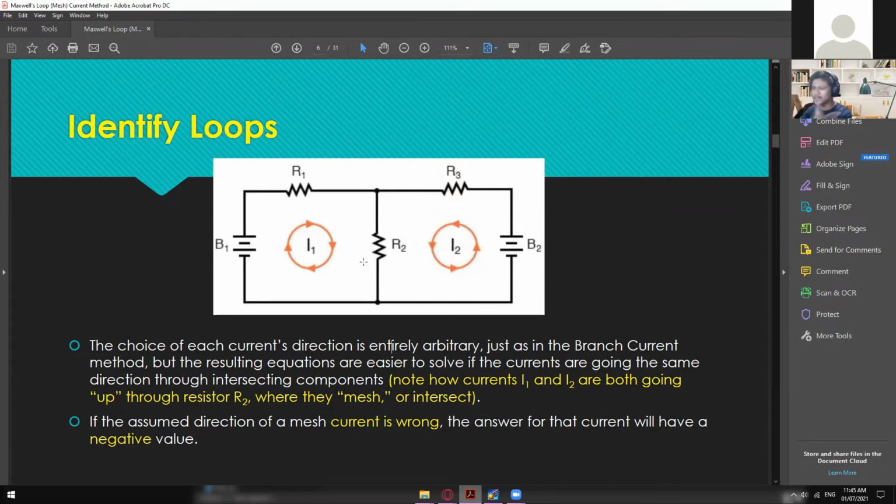So how do we identify again the flow of that mesh or of that loop? In my case, I always base it on the outer part of the voltage source. So in here, I always go with the positive leaving polarity of the voltage source. So wherever is a positive, that is the flow of the current.